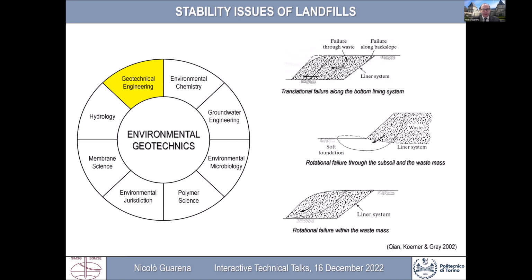The occurrence of several huge landfill failures in the recent past emphasizes the importance of an adequate understanding of soil mechanics when designing waste disposal facilities. As far as the failure mechanisms of landfills are concerned, in addition to the rotational mechanisms that are prompted by soft foundation soils, steep waste slopes, or poor waste compaction, the translational mechanism with the waste mass sliding over the lining system at the base of the landfill has resulted in the largest failures to date.